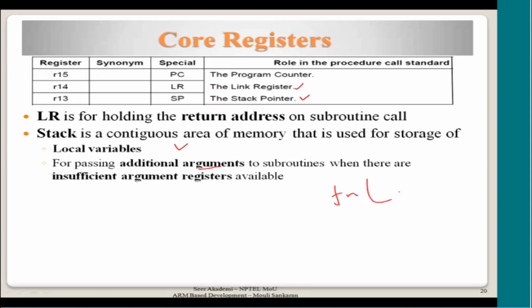So when you are calling a function, the language doesn't restrict how many parameters you can put. Maybe there are some limits, maybe the tools may limit it, because you can't have thousands of parameters, but still it is not just 1 or 2 parameters. You can pass even 11, 20, 30 parameters. In that case, when we pass more parameters, the architecture allows some optimization. A few registers are allocated to pass parameters. I will explain that in a minute. The parameters can be passed in the register rather than in the stack.